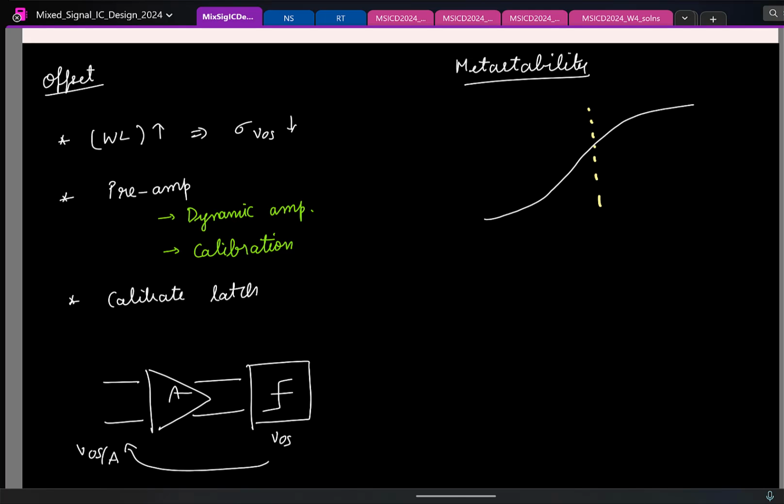At the end of this clock phase, the output might not have reached a valid logic 0 or logic 1. That's an issue, and again it is because the input to the comparator is really small. So what is the natural solution? You put an amplifier, so this preamplifier will help you here too. This is where we stopped.